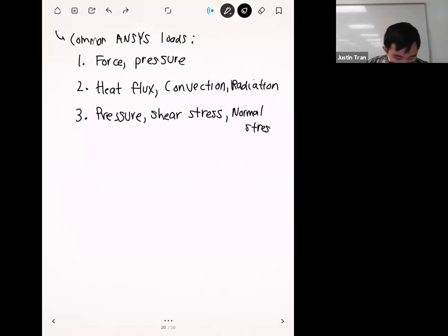You guys know what forces and pressures are. Even though we think of these load type boundary conditions as the main instigators for interesting action in your finite element simulation, if we go to the doc cam from earlier, when I karate chop it, that's providing a force. I'm not directly saying that the displacement has to be a certain way. I'm applying a force onto this guy. But strictly speaking, load type boundary conditions are not actually required.